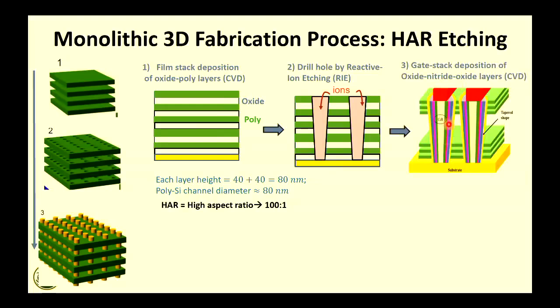So this is your gate stack. Your channel is now vertical, right? And the cross section of this green layer and the memory hole, that is defining your one cell. So this is your one cell from, say, word line 1. This is another cell from word line 2, another cell for word line 3.